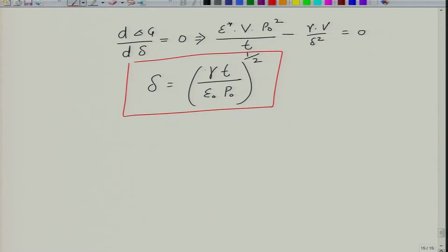That makes sense. Higher the interfacial energy is, so this is like grain boundaries. Higher the grain boundary energy is, larger the grain size is, because you would like to minimize the surface energy. So, any increase in gamma will prefer bigger domains. Similarly, if you make the crystal thicker, the charge density per unit volume of the crystal also goes down, which means you can manage with bigger domains.